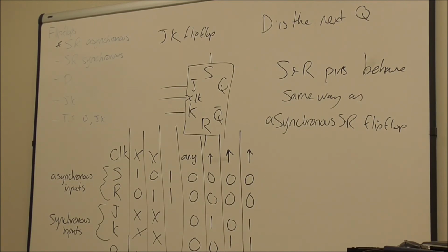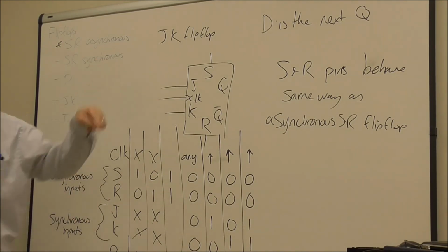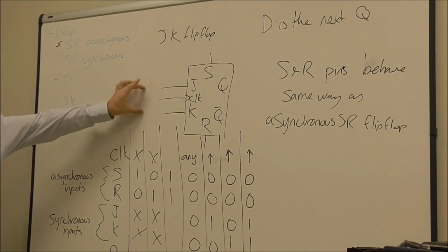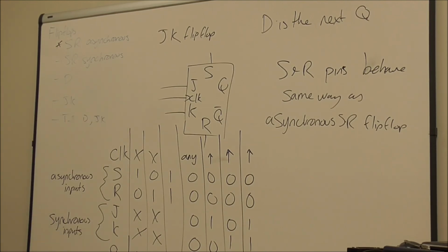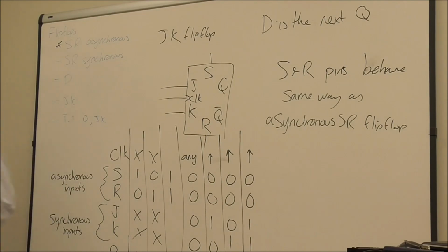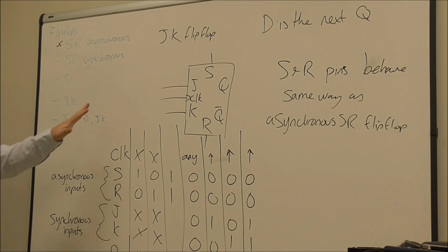So in the same way as when we wired up the D-type flip-flop to have D connected to Q bar, if we have both J and K set to 1, it makes it a toggle type flip-flop. So this is an important distinction between the JK flip-flop and any of the other types, in that it has a built-in toggle mode depending on what the logic level is. Okay, anybody got any questions about the JK type?